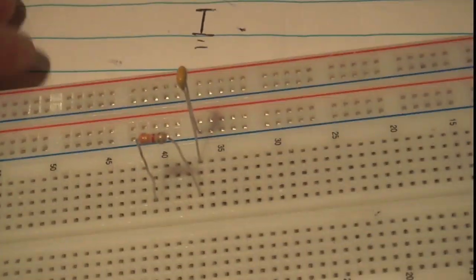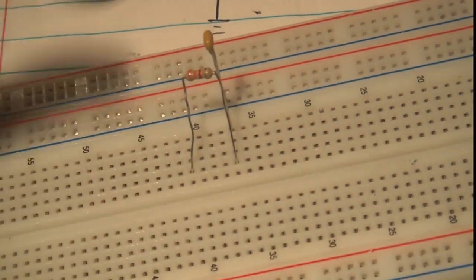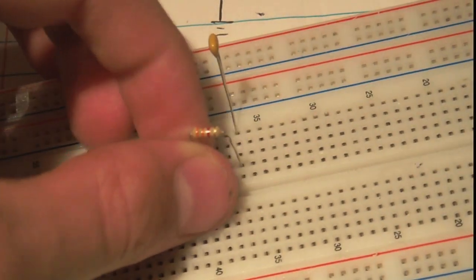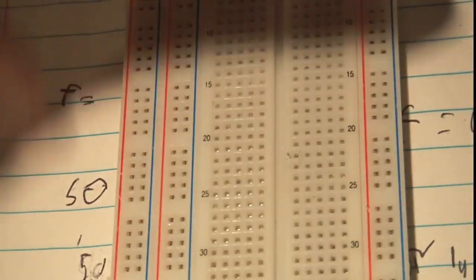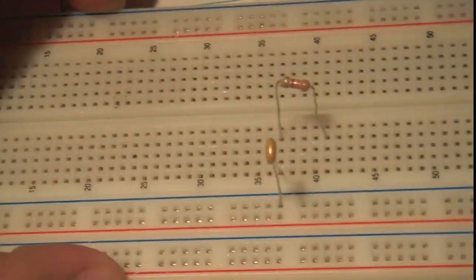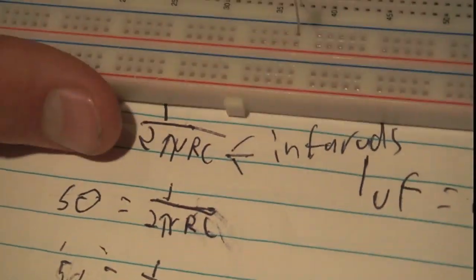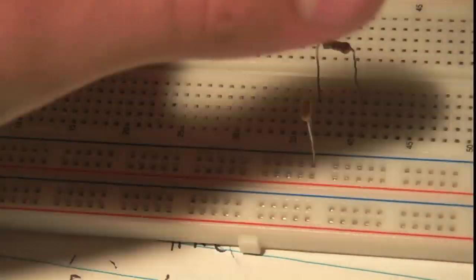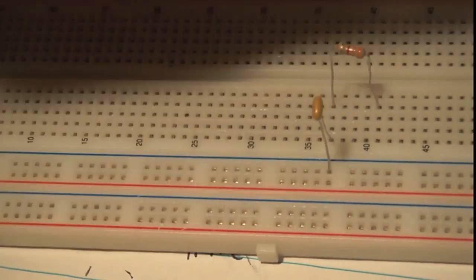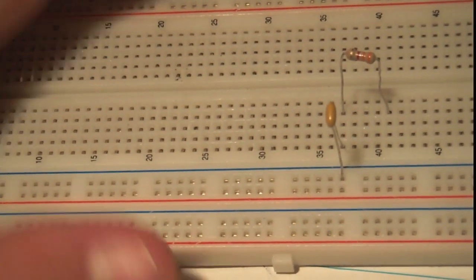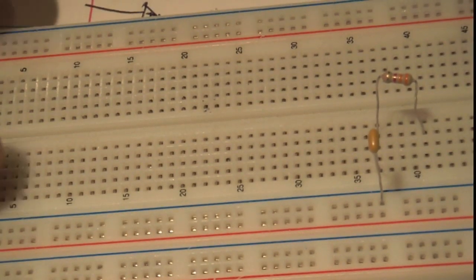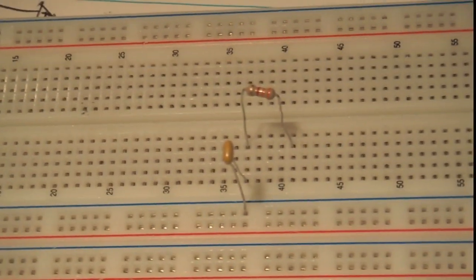Now I'm going to put in the buffers. I'm not going to show you how to do that; you can do that on your own with some op-amps. I'm just going to use an LM324. Not super high bandwidth, but again, we are working with very low frequencies. Then we're going to measure this filter. We're going to see how effective it is at changing PWM to an analog value, and investigate some of the characteristics of its frequency response.